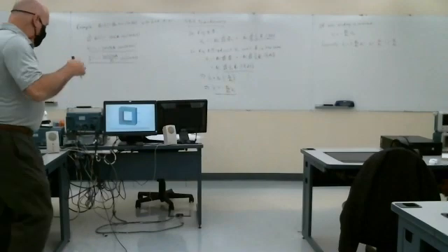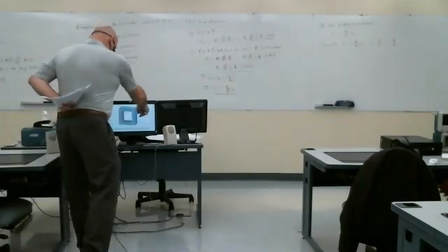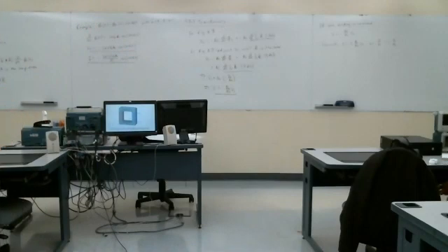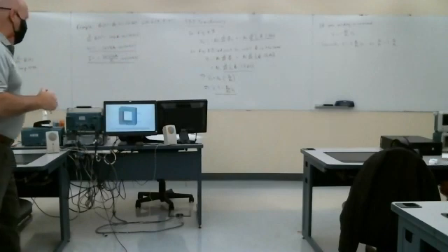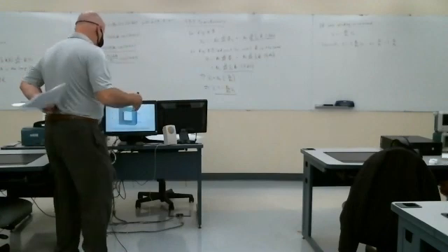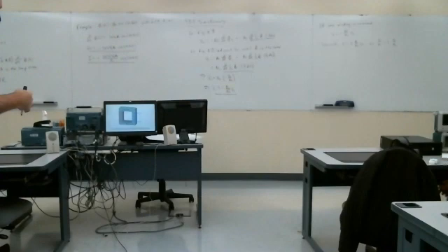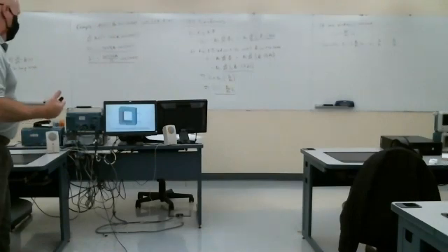Again, you could assume either polarity for V2 here, and a toroidal coil would be used to keep the flux confined to the core. But here they've shown V2 as being positive at the bottom. So the question becomes, do we use the minus sign or plus sign for the relationship? And that depends on the winding of both coils.